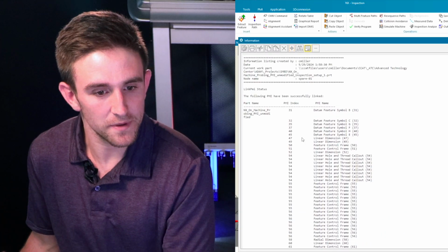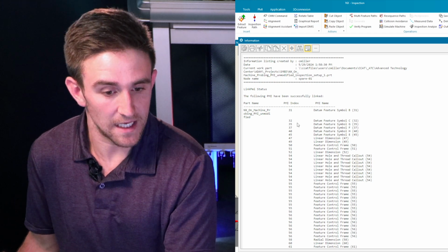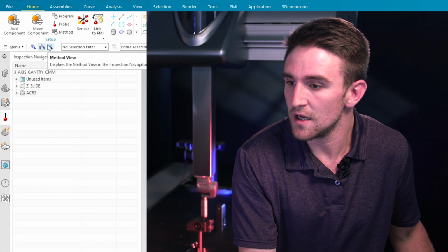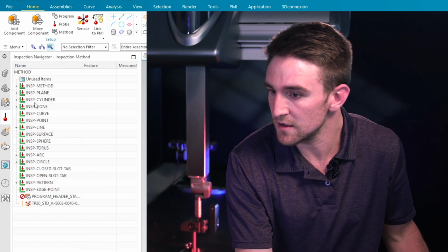Now I have a pop-up that shows me all the PMI that has been imported correctly. Sometimes you may see things that are imported but not linked successfully, or things that are not recognized at all. Yep. Typically that means your PMI is incorrect and needs to be updated to the right format so that it can be read. Yep. So in this case, again, we have everything successfully read. I'm going to go into the method view right here, which will show me the geometries that can be inspected.